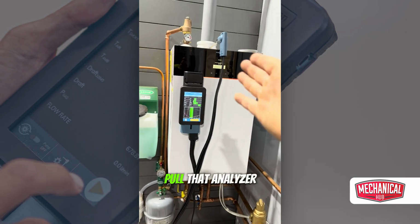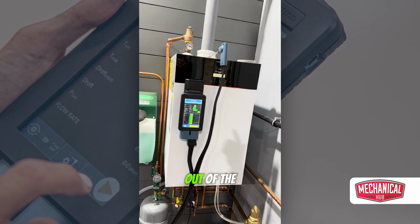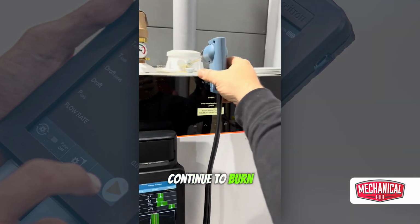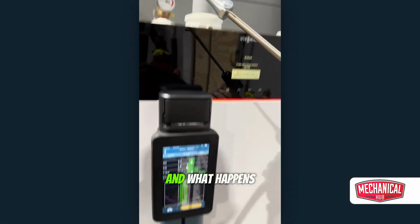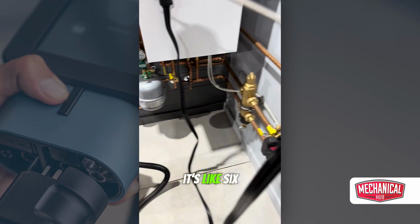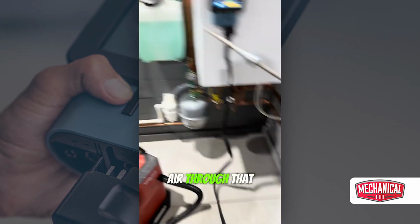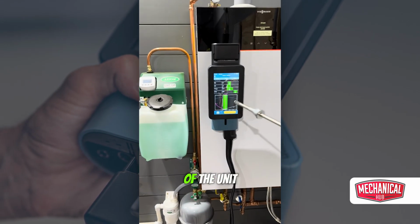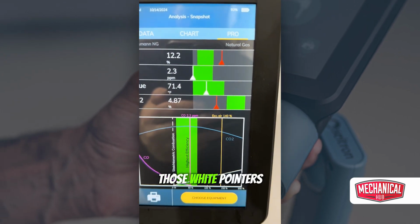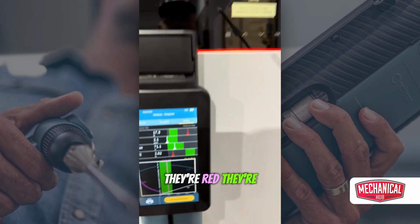Now let's take a look at what it means. I'm going to pull the probe out of the flue gas. I'm just going to let the boiler continue to burn. I'm going to just pull it out. And what happens is, because that's a very long hose, like 6, 8, 10 feet, something like that, it's got to suck air through that all the way to the pump of the unit, and it's going to start showing us, whoa, those white pointers are no longer white, they're red. They're way off the charts.